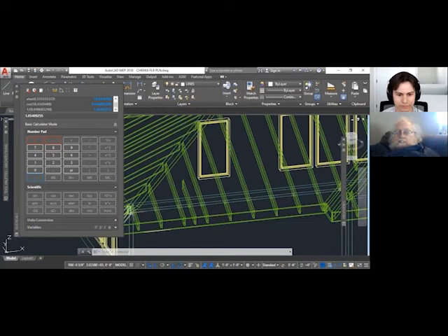And we subtracted that 2.47 from the distance that we measured from the corner to the long point side of the jack rafter. And that gave us the distance that our rafter is going to travel this way, because it's going to go the same distance this way as it is this way. And then we simply took it up. We multiplied it by 1.054. Bingo, we've got our first jack.